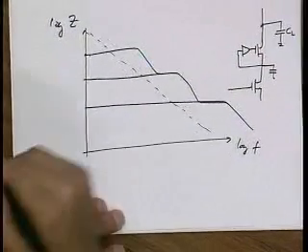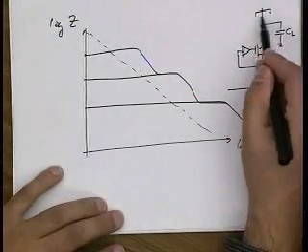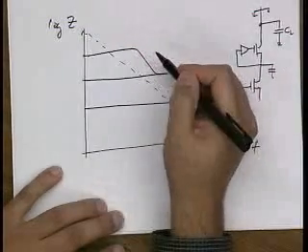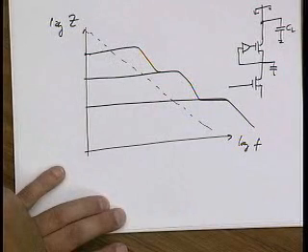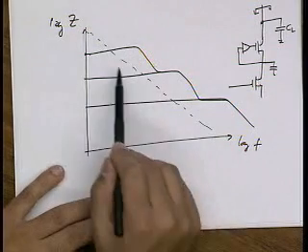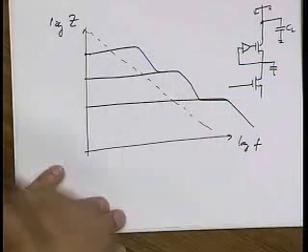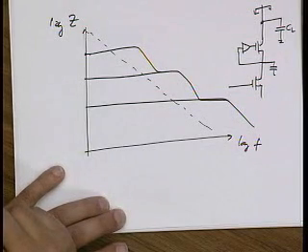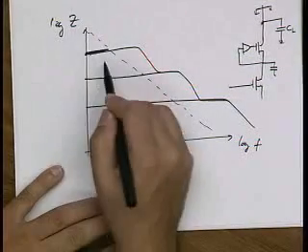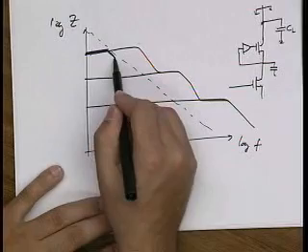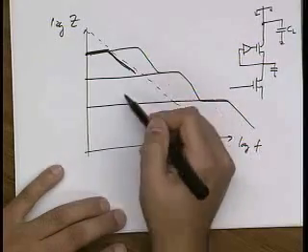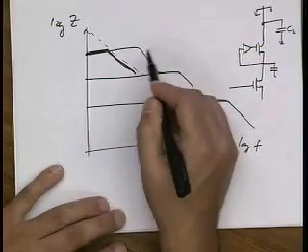But the idea is that the overall impedance looking out here is a parallel combination of CL and this guy. So the parallel combination, of course, is dominated by the smaller impedance. So at really high frequency, it's really this curve that dominates, right? These other curves have almost a negligible effect. So if I were to plot the impedance as a function of frequency, at low frequencies, this curve dominates, and then basically I more or less follow this curve. I'm slightly below this curve, because it's a parallel combination. So the parallel is smaller.